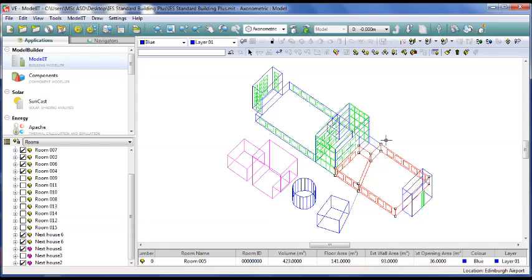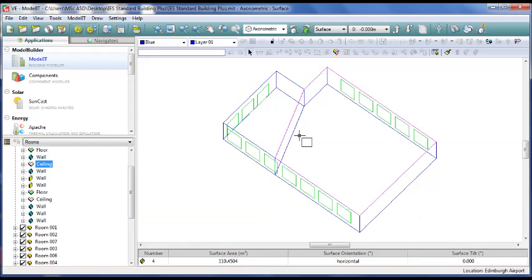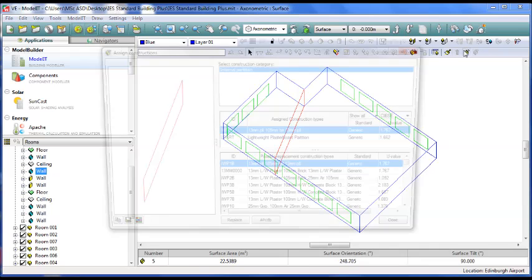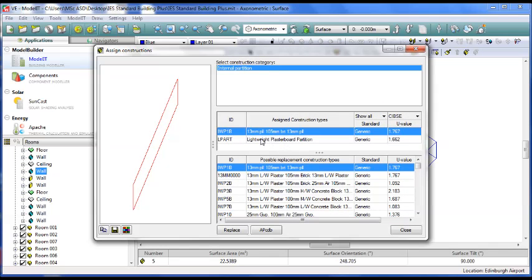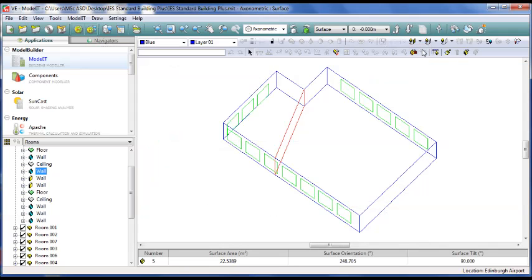And all I need to do to get rid of the construction line is click the other button and it's gone. Now if I go down a layer, highlight that wall and see it, it's actually made of a pre-decided partition material. So the starting point here is that this partition, as you can see, is made up of that construction, which is plasterboard with brick and then plasterboard, which means it'll have a white surface to both sides. So I'll just close that for now.